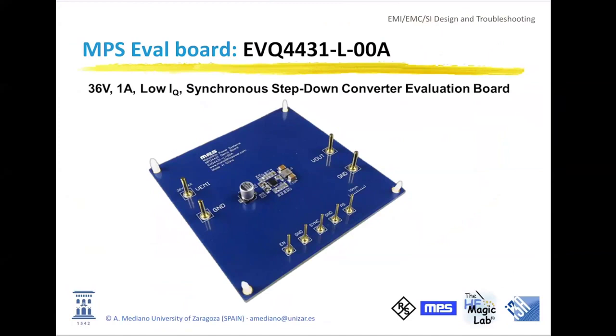The previous DC-DC converter was created with bad techniques, considering the size of the switching node, the distance between the components, the ringings, etc. In this case, we have a 4-layer PCB, and I will comment later on some specific ideas that are useful for this PC board.